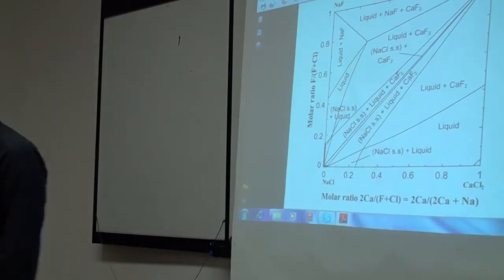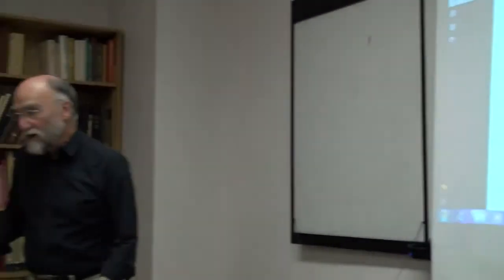We do this in FactSage when you're using the phase diagram program. You will see that if you're choosing composition variables, all the composition variables have to have the same denominator. We do that simply to ensure that you get diagrams with straight tie lines. Otherwise, you can get a diagram without straight tie lines and not realize it. So that's what that's all about.